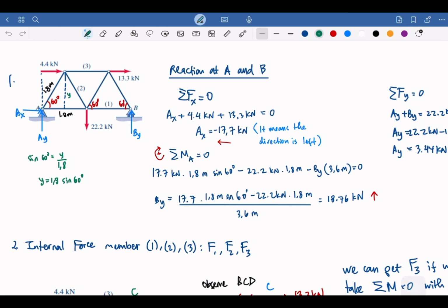Remember that every force in physics you can move around, as long as it is along the same line of action. You can basically move a force around without a distance, it has only direction. Right? So you can move this 7.7 there, and then use that for y. Okay, this distance y. So that's this one. Okay, and then we have this 22.2. Okay, it's easy to see. Okay, that way. From my perspective, I will make clockwise positive.